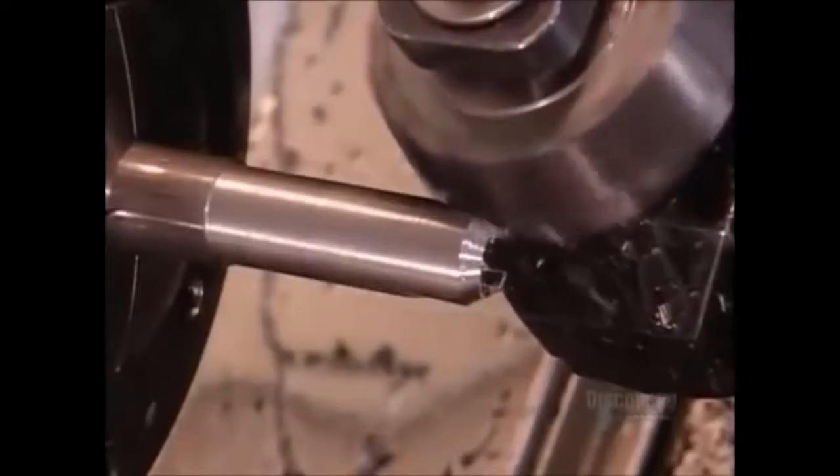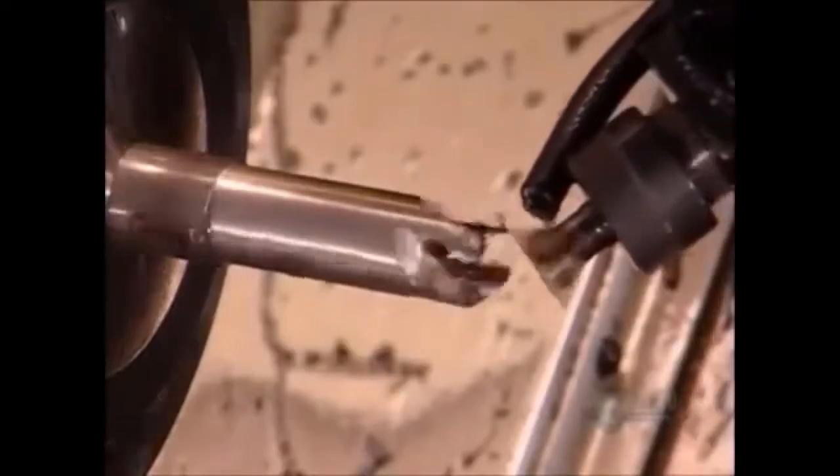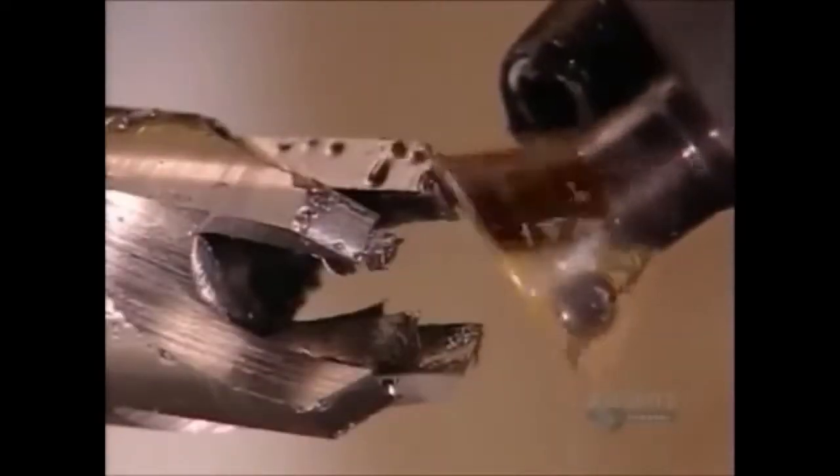Some plug cutters on the market have fewer blades. This company makes 4, so the cutter will clear the wood chips more efficiently when it tunnels into the wood. After the dovetail cutter sharpens the blades, a tool called a boring bar refines the hole in the center, making it the proper size. Another turning tool now forms the shank, the stem of the plug cutter that you insert in the power tool. Then the cut-off blade slices the tool off.